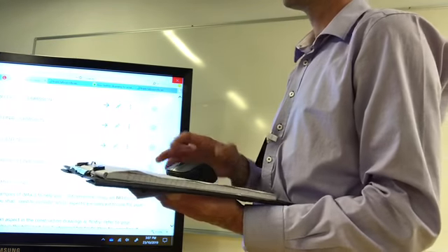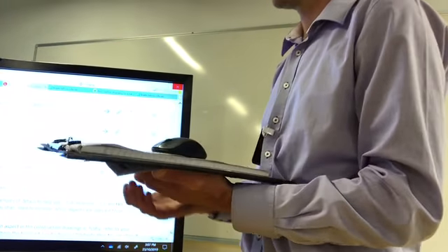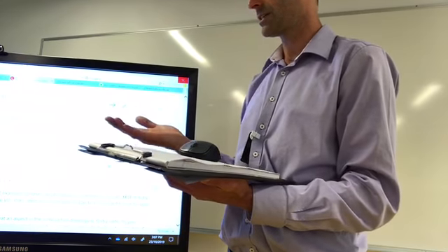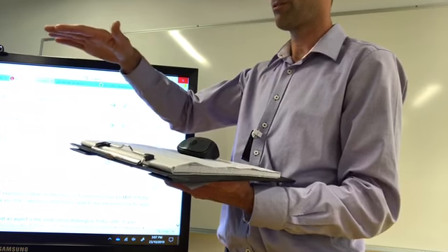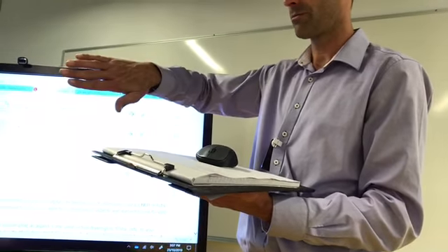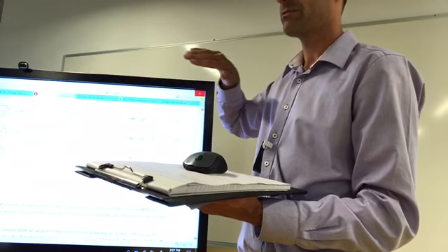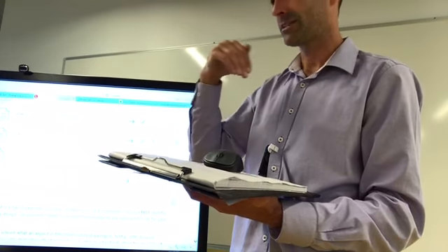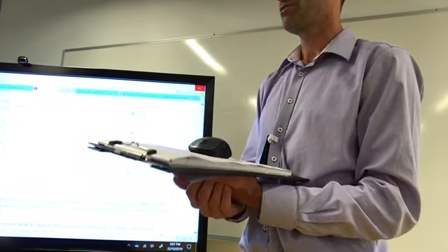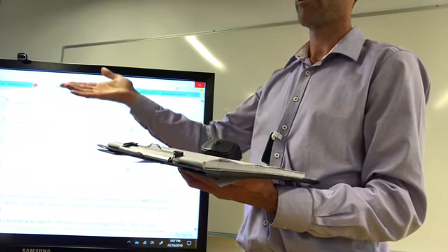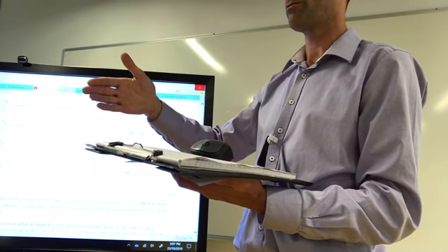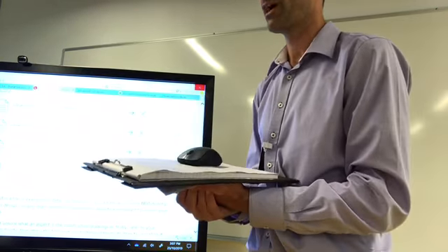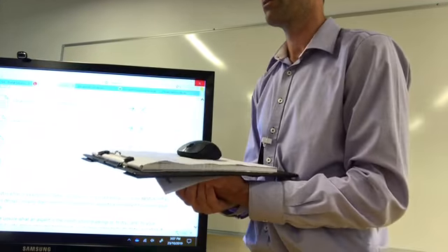But I think the better detail... I've seen details for a flexible flashing to go over top of the EPDM membrane, and then that's fixed to the back of the parapet with a sealant at the back of that. But I think a better detail is to actually carry a flashing all the way down the side of your parapet and lap over that flexible flashing over top of your EPDM membrane.